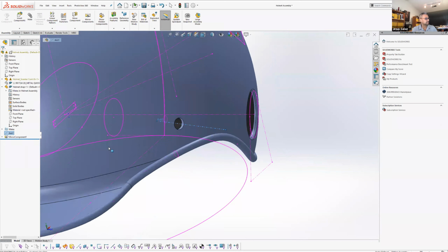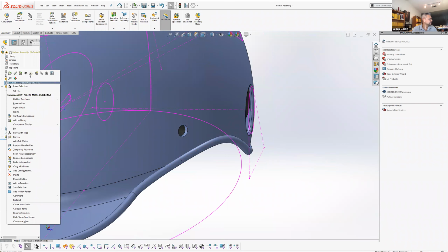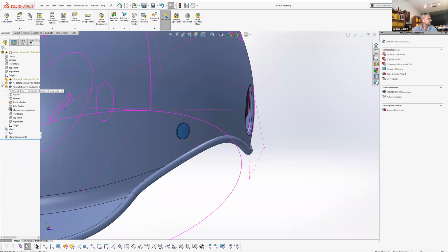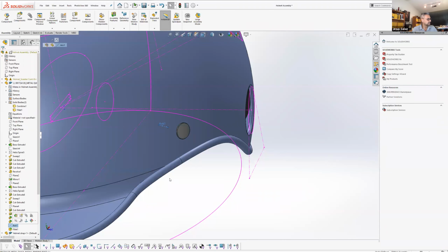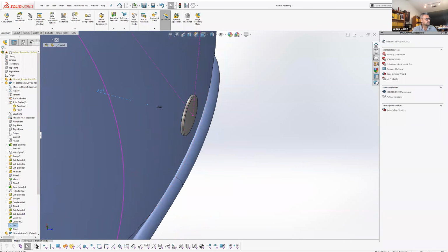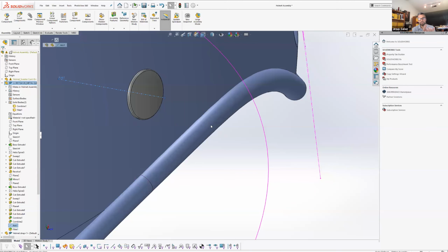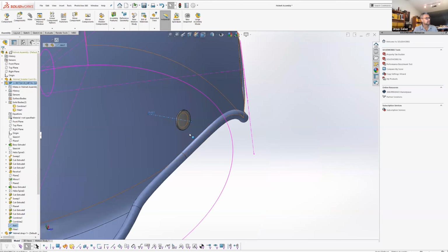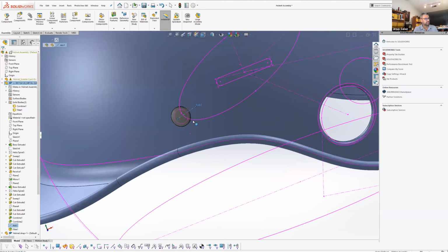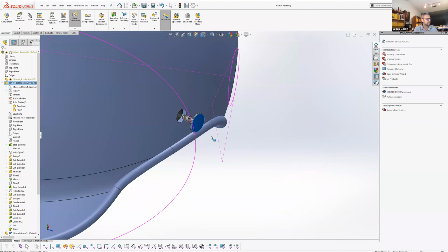I need that to mate it to the screw, or in this case the rivet head there. So I created an axis also on the rivet model, just to make sure I have an axis there. And then I just mated both of those axes so that they match up. Even if I change the location of that hole later on, that rivet's just going to follow it, because it's SolidWorks and it just follows that stuff.